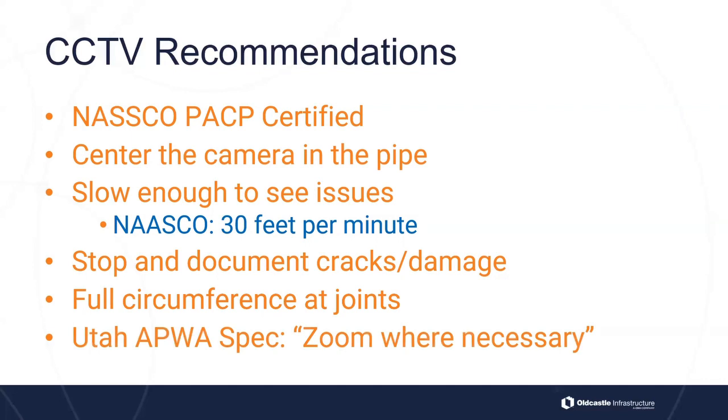So if we're zooming in only where necessary, that's good. But we've got to be really careful when they zoom in, because some of these smaller diameter, 12, 15, 18-inch pipe, the more you zoom in, the larger these issues are going to look. So be very careful and leery when we're zooming in on CCTV.